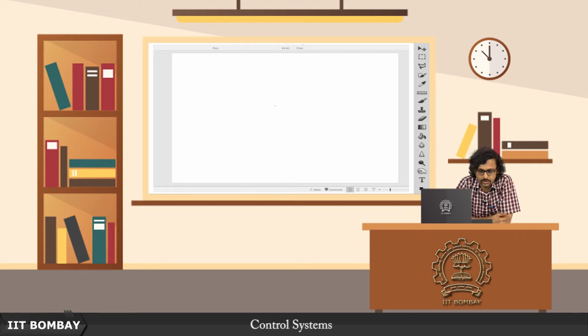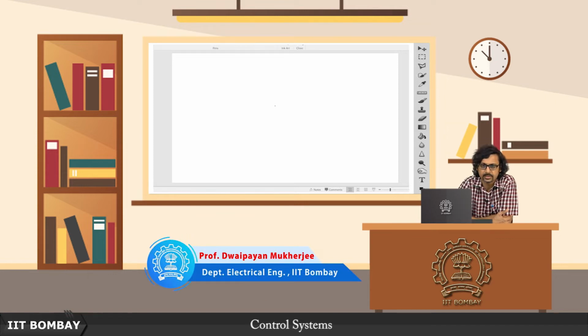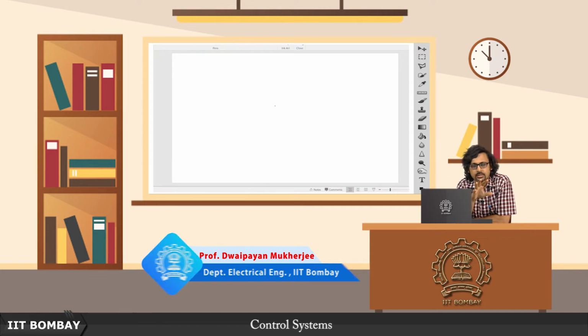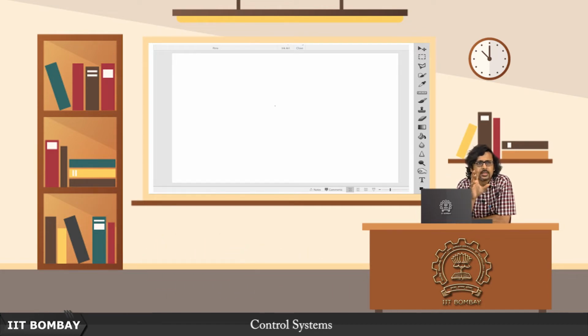Hello and welcome to another lecture on control systems. In continuation with what we were doing in the previous lecture, we saw that apart from these two earlier preliminary realization methods of state space systems from transfer functions, there was also this diagonalization or diagonal form of the system matrices, where the A matrix turned out to be diagonal when you had distinct poles that were real.